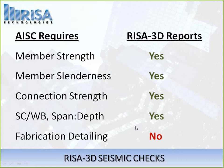so that we can talk about what results we're going to be reporting within the program. Now, the AISC requires us to check member strength and slenderness, connection strength, some miscellaneous checks such as strong column weak beam ratios and span to depth ratios, and then there's also a number of fabrication detailing requirements within AISC as well. We will report to you checks on everything listed here except, of course, for the fabrication detailing requirements.